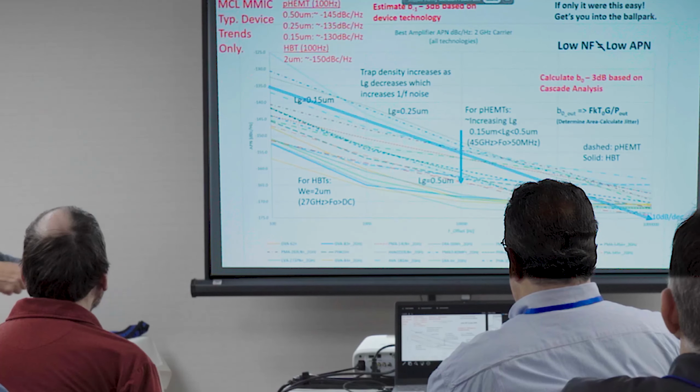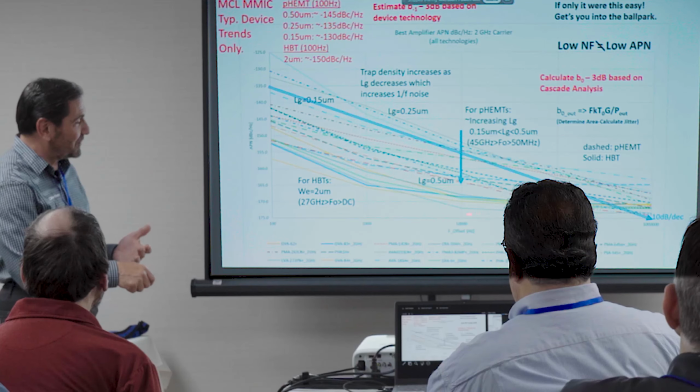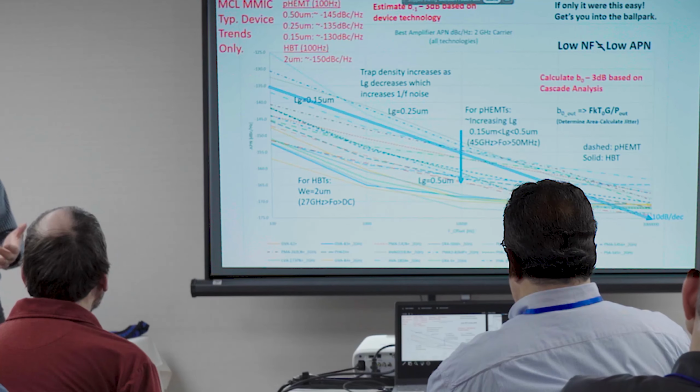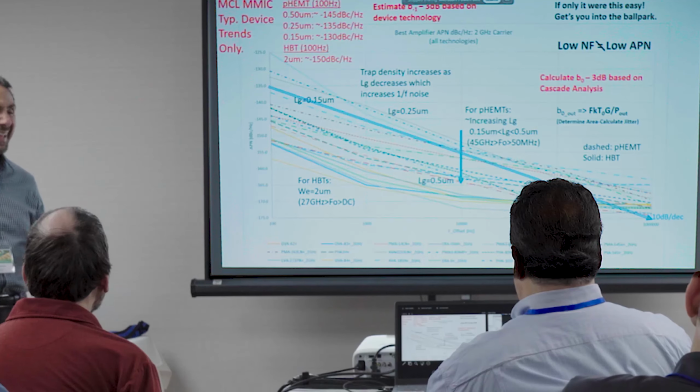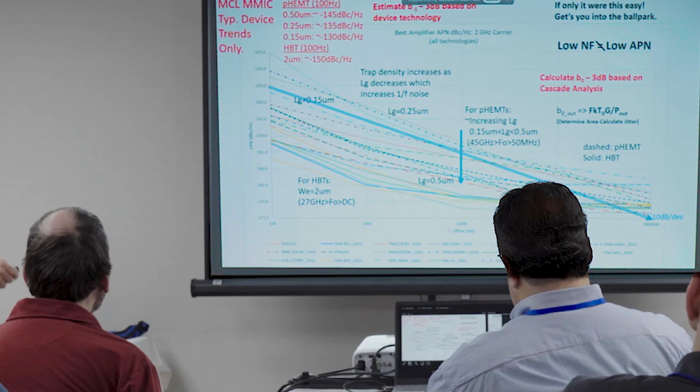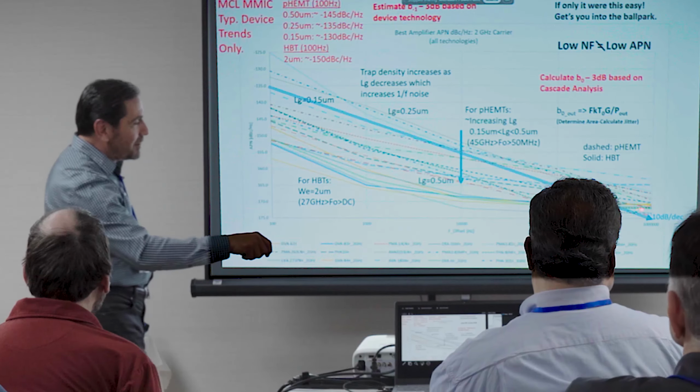All right, well, maybe then you can start to consider this. But boy, this thing hits the noise floor at around 10 kilohertz. These don't hit the noise floor till above a megahertz. So be careful with these rules of thumb. You have to understand what they imply. So yeah, maybe if I get over here somewhere, I might come below this curve.